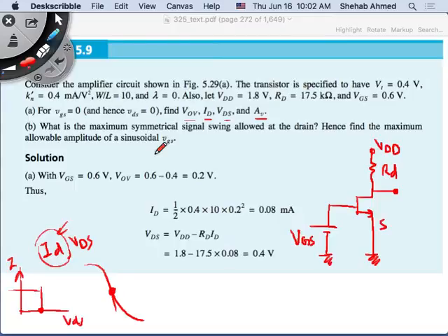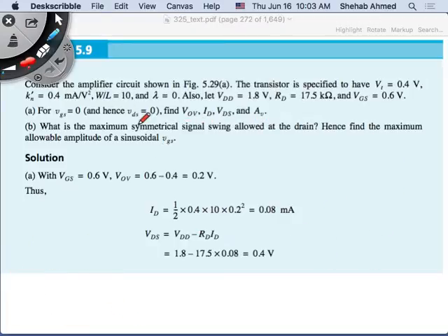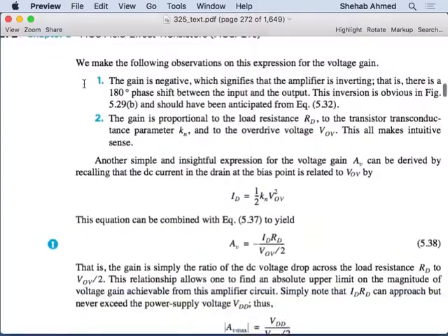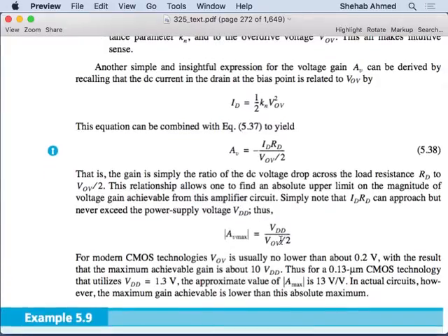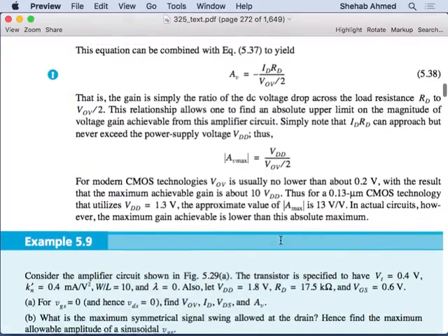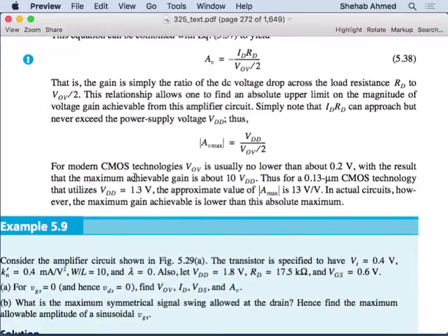It tells you that the gain is really limited by the power supply voltage and the overdrive. So how much gate you have is going to define gain, and what's your peak value of supply voltage. It's nothing, I mean, it's just a manipulation of the equations.